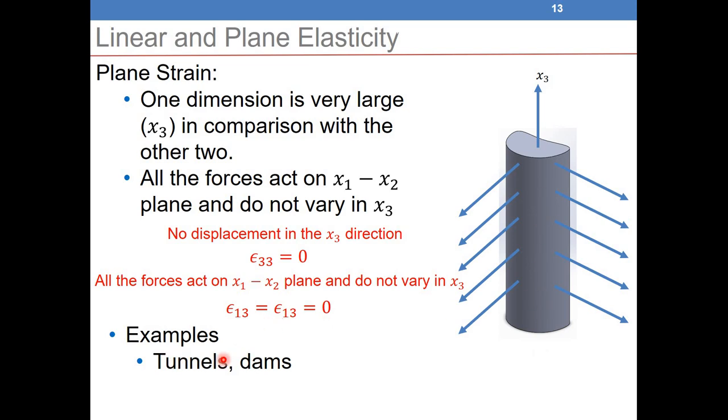For example, here we have two examples that we use in engineering, the tunnels and dams. We will see now how we can do this, but for this slide you need to understand that for thick plates, if the plate is very thick and I don't have any force acting in the direction of the length of the plate, along x3 here, in this case I can go from 3D strain to 2D strain.